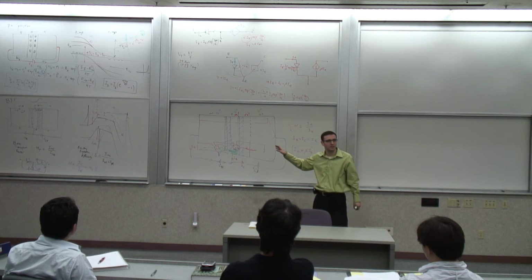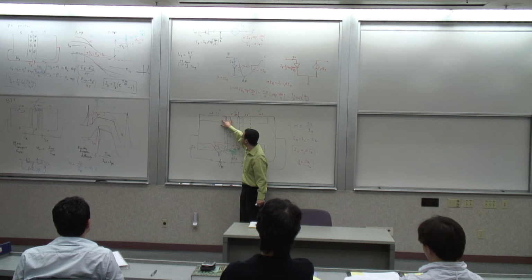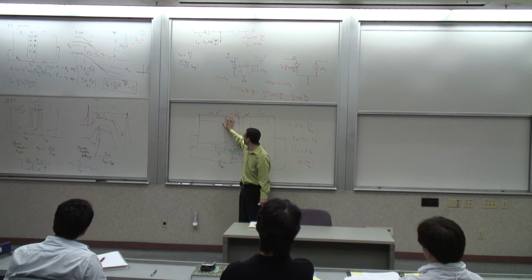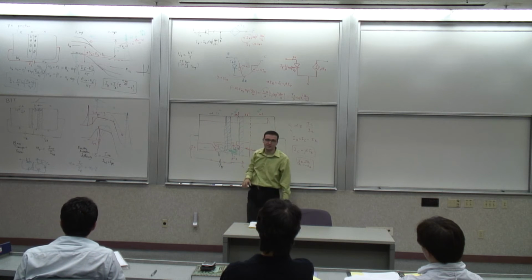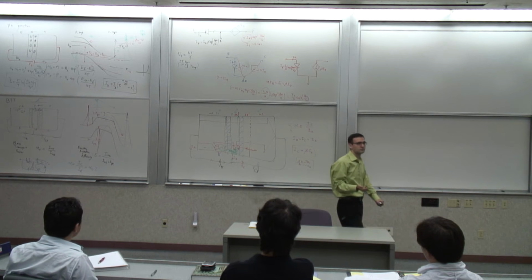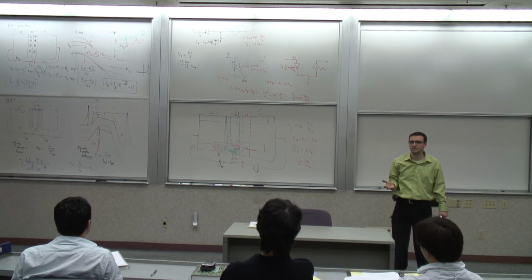Does that make sense? So it's an indirect effect. The fact that I don't need such a large difference because I have a lower band gap here and there allows me to increase this level and hence increase this level while maintaining this ratio constant. So without degrading my Early effect, I can maintain the same gamma with the aid of the difference in the band gap and hence improve the situation. Okay? Does it make sense?